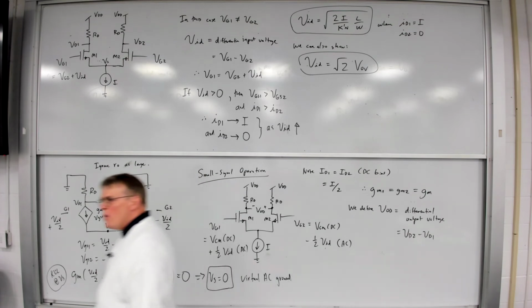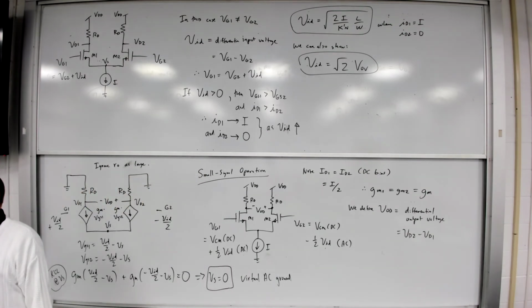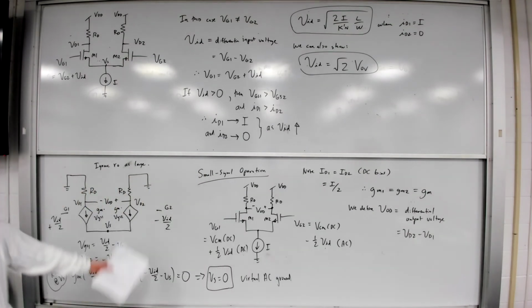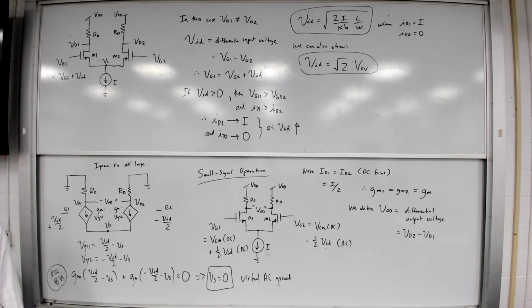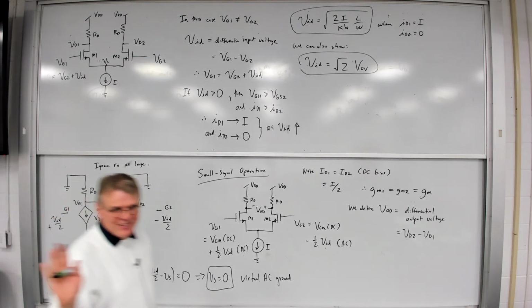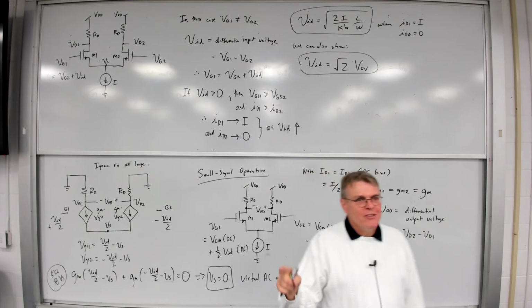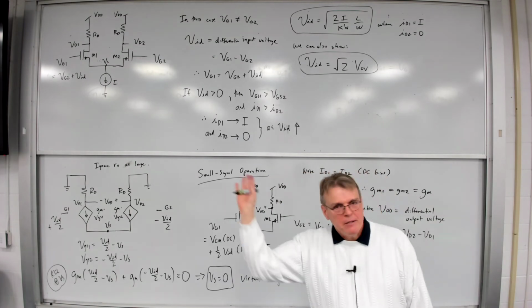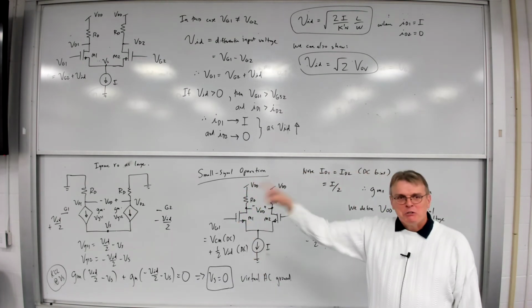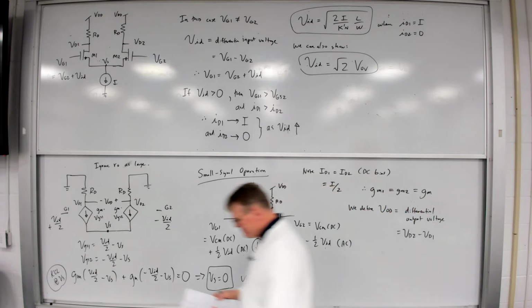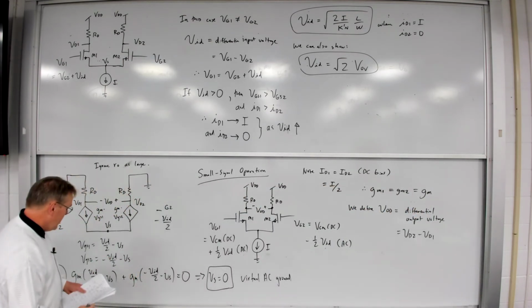I can now get that source voltage at 0 without the need for a large capacitor. That is really useful because now we've gotten rid of one of the things that limits the gain. We don't need that capacitor anymore. That's extremely powerful. Okay? Now we can go through